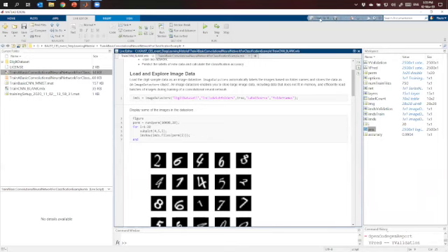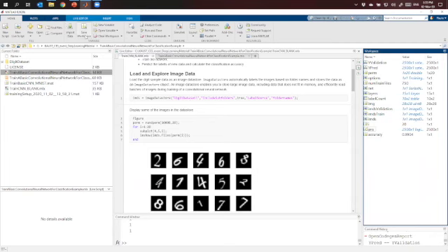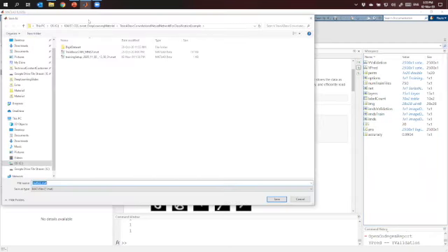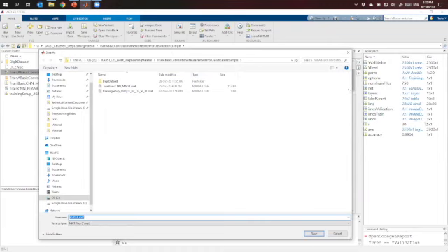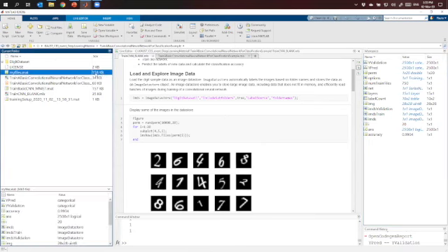So what are you going to do now? You're going to clean up everything. Let me show you how to clean up. If you want to save what you have done in Matlab, you can click here in the Home tab, Save Workspace. What's going to be done with this action? You're going to save everything that is here in a file, a MAT file. And after, let me name my files. Save. I recommend you to do that, okay? So you will not miss your files. So it's saved, my files. It's not a lot.